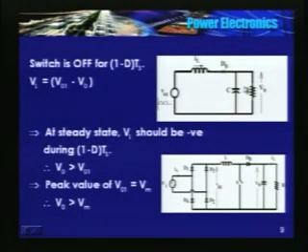In this circuit, if you see, L is constant, and the duration for which S is closed is also constant. Therefore the peak value of the current is given by VO1 divided by L, and we assume that the switch is closed and opened at a very high frequency, and during that period VO1 will remain constant. Its value is proportional to the instantaneous value of VO1, but then VO1 itself is varying sinusoidally, therefore the peak value of the current will follow a sinusoid.